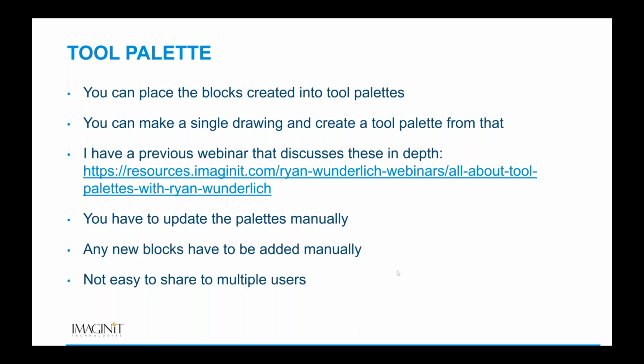A couple of things to know is you have to update the palettes manually. Any new blocks have to be added manually, and it is not an easy process to share this to multiple users. Okay, so there are some pitfalls with it. It's not easy to share. Everything is a manual process to update from there, but tool palettes work nicely.